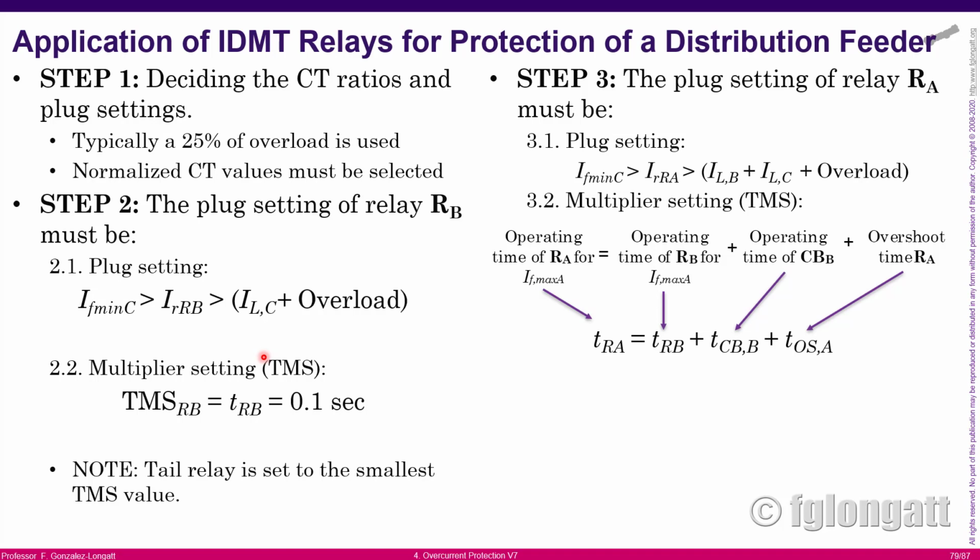In this case, we will use 0.1 seconds. It's typical that we select the smallest time setting for relays located at the tail of the feeder.